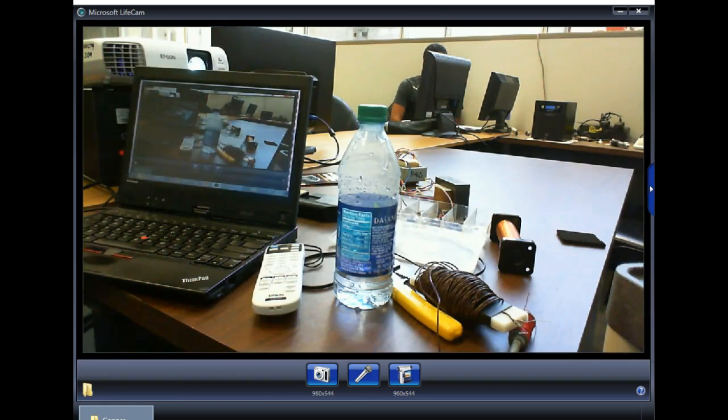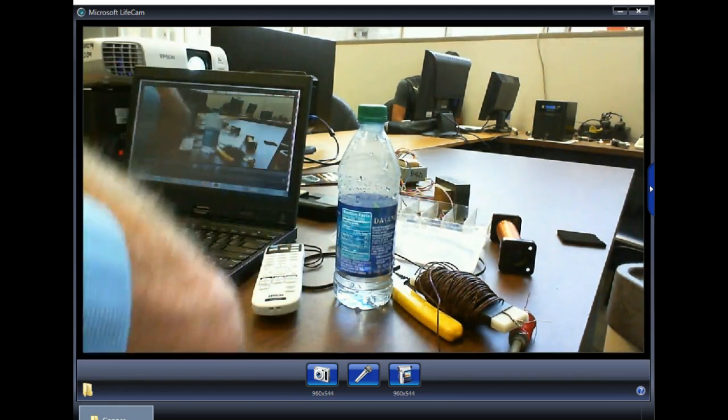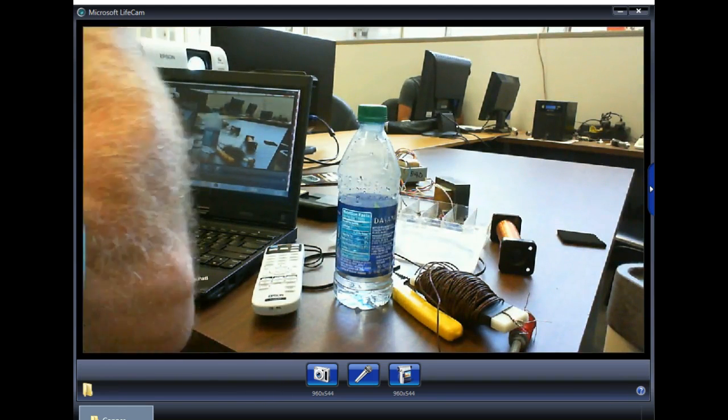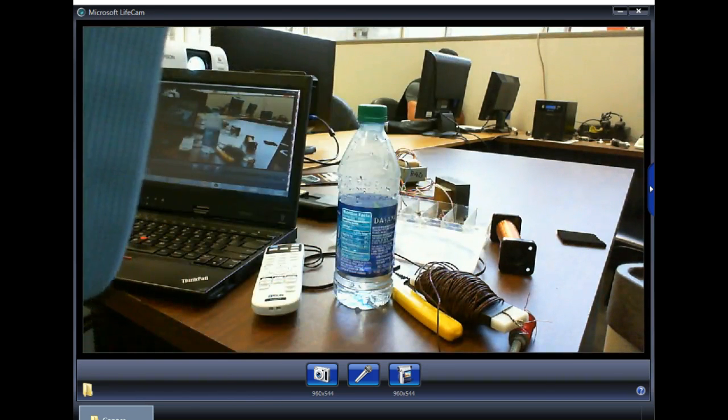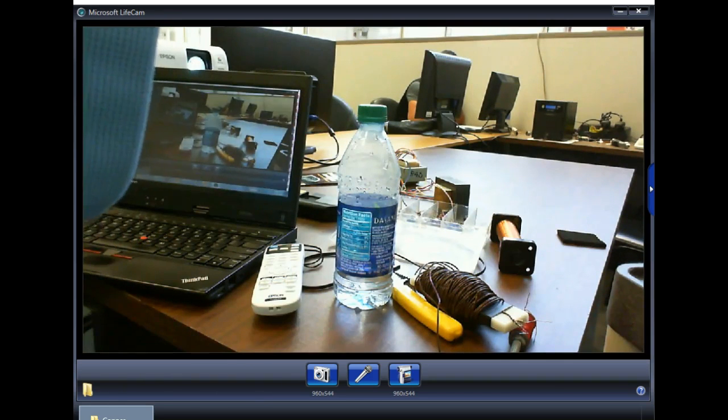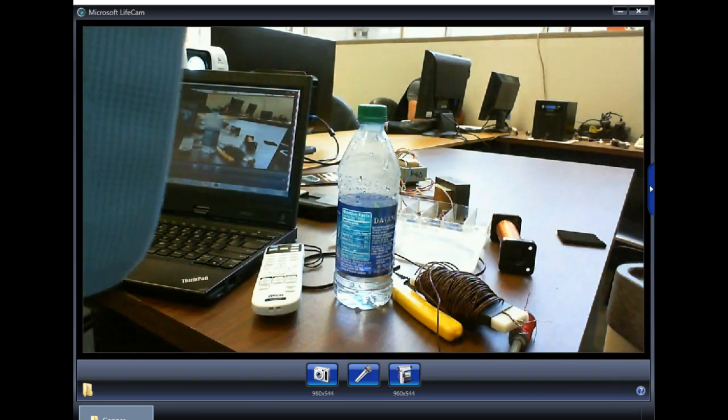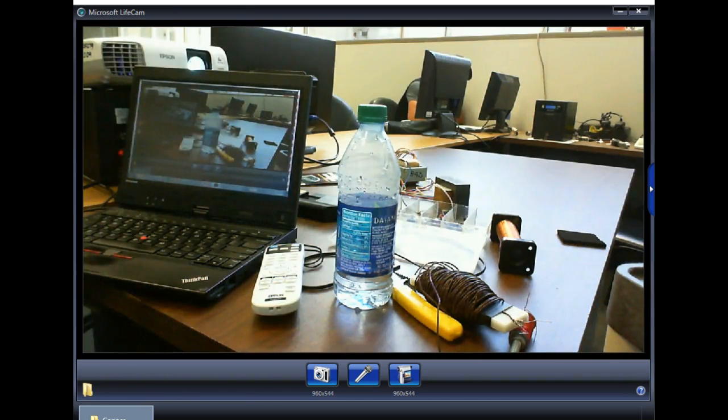So if you bought a 20 amp device, it would have a plug that uses that little thing in there. So that means I couldn't plug it into a 15 amp receptacle, right? Now I can plug a 15 amp device into this thing because it's rated at 20, but I shouldn't be able to take a device that needs 20 amps and plug it into a 15 amp receptacle.